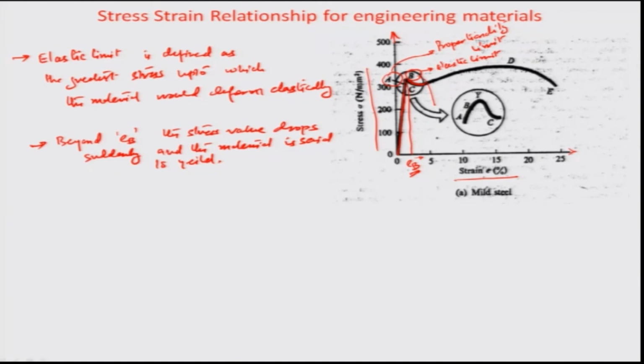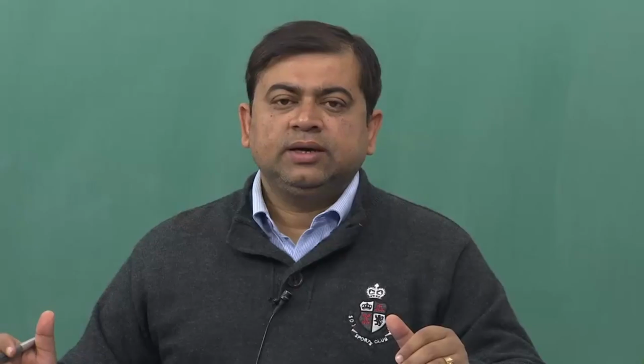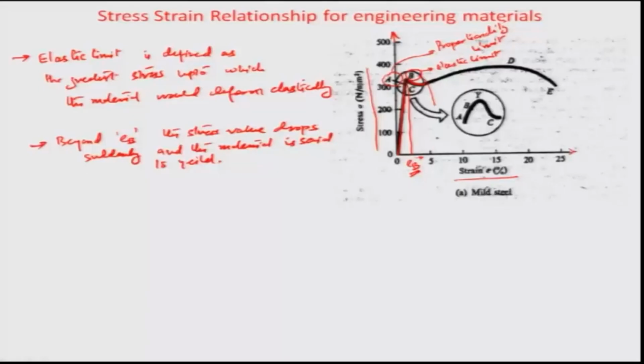So, this is actually a very strange situation that if you are applying, let us say, the same constant stress to it, the strain value keeps on increasing because of that. Okay. So, in other words, it does not resist as much the external force as it was resisting before. So, the point y above the point b is not visible really here, but if you look at the way b goes, beyond b there is a point y, which is also known as the upper yield point.